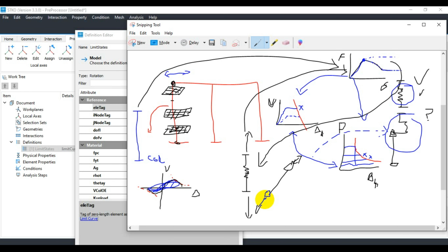These parameters include the strain degradation, which is very important, and I discussed this here as well, in terms of triggering a warning to OpenSees that if the limit is reached towards collapse, you have to trigger the warning and reduce its capacity. The shear critical columns as well are important here.